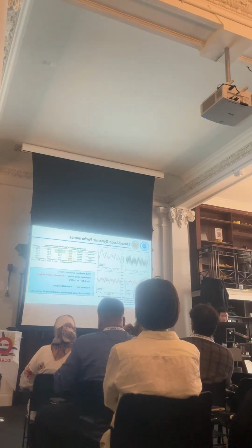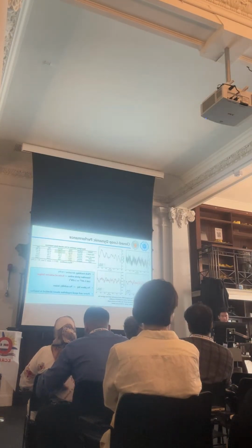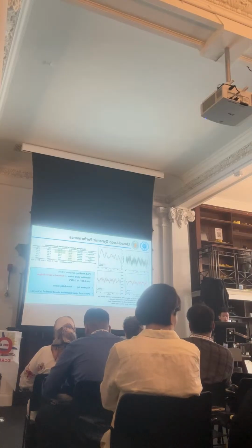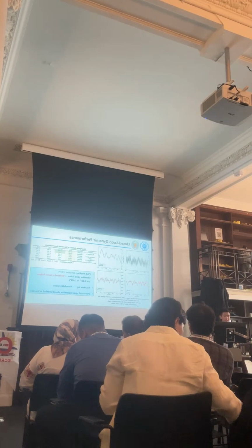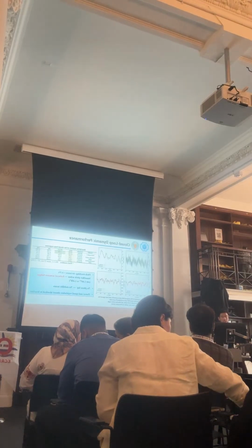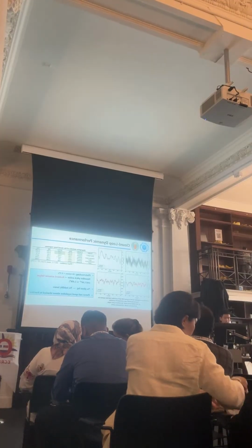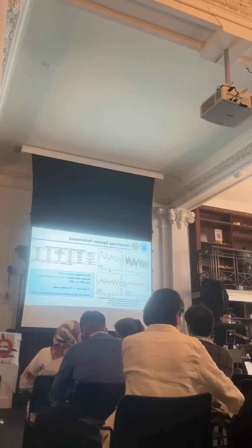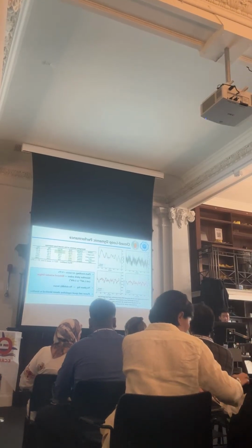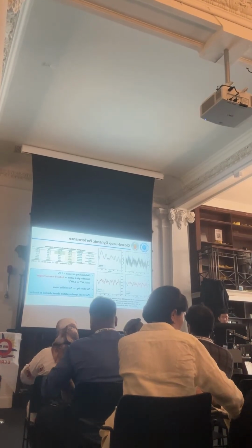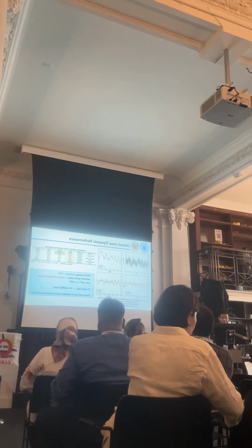The mean value of the pitch angle differs by less than 0.5%, which is almost negligible, but most importantly, the standard deviation of the pitch angle has a lower value for our RBF controller. That means it can have a smoother pitch action, and also help reduce actuator fatigue.